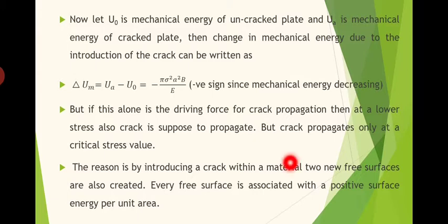So when the crack is introduced, two free surfaces are also created. Every free surface is associated with a positive surface energy per unit area. Actually, this positive surface energy per unit area is nullifying this negative change in mechanical energy.